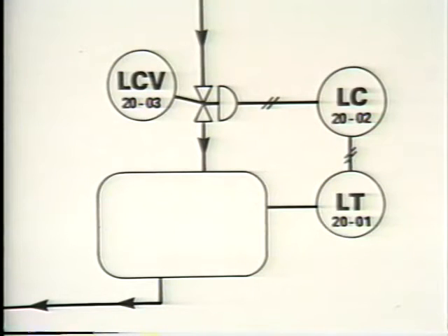The lines that connect the instruments to each other and to other components tell us how the different parts of the systems relate to each other. For example, lines with hash marks are standard indications for pneumatic signals. So these instruments send pneumatic signals through the control system.